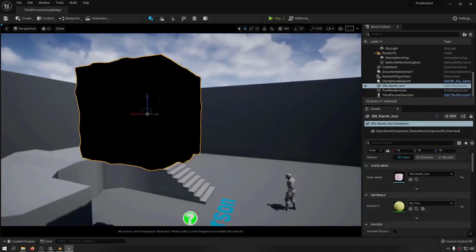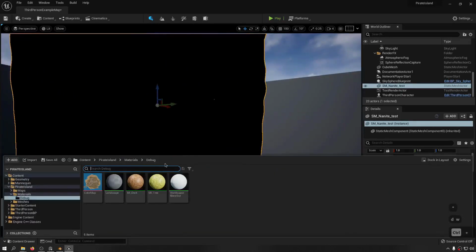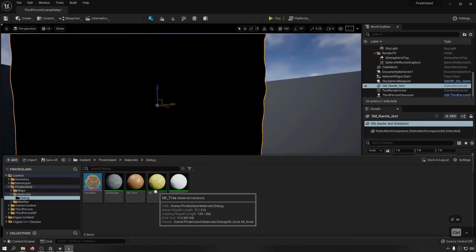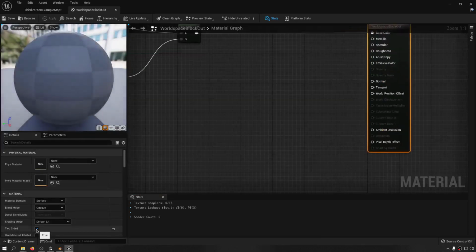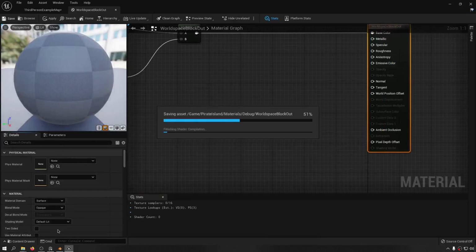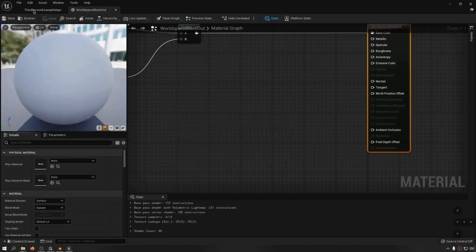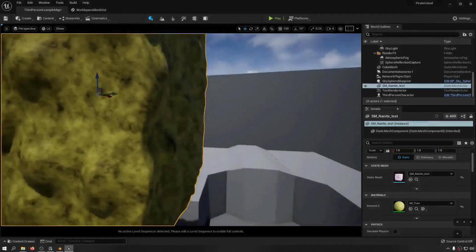And it converted into black because nanite currently doesn't support the two-sided material. And you see this is a tree material that in here we enable two-sided. Let's disable this two-sided for now. Nanite isn't accepting the two-sided material right now. They might change it in future, but for now it's not accepting. So let's give it a little bit of time to calculate.